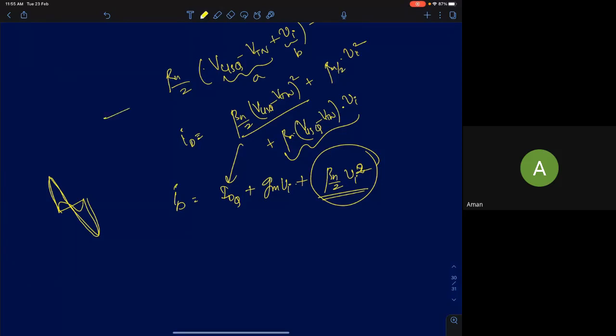This is the actual drain current, comprising both the small signal and the DC current and all of that. That's what happens in a real circuit. But we just focus on this term. Anyway, we are assuming it's biased, so we remove the DC part. We'll focus on these; in fact, these two are small signal parts. What I'm trying to tell you is that the small signal approach you use for calculating gains is an approximation. There is also a nonlinear term present, which we are ignoring in the analysis.